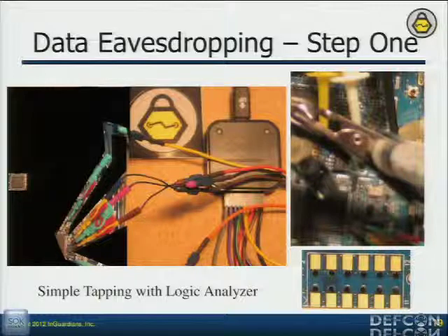So it's really tough. What we do is we look for debugging pads. Most of the debugging pads are for JTAG interfaces, to reprogram microcontrollers so that the developers have an easy way to push firmware up into the memory components. But when we're going board to board, sometimes we have those as well. And the board-to-board is going to show the communications that are passing between the NIC and the metrology board.